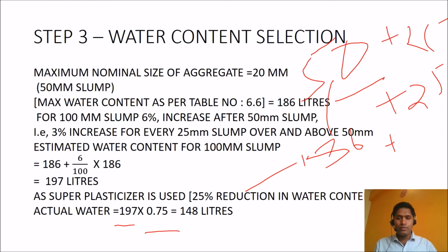If you design the mix in Bombay, the admixture usage will be very high, which in turn means the water reduction will be less. Whereas if you utilize it in the Bangalore climate, you can reduce the admixture content to a nominal amount, whereas the reduction of water content can be done to a maximum extent.